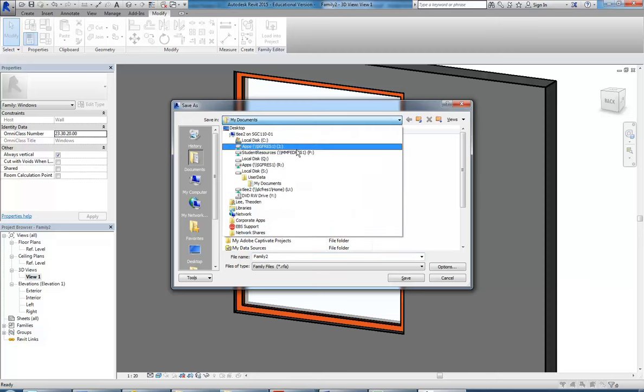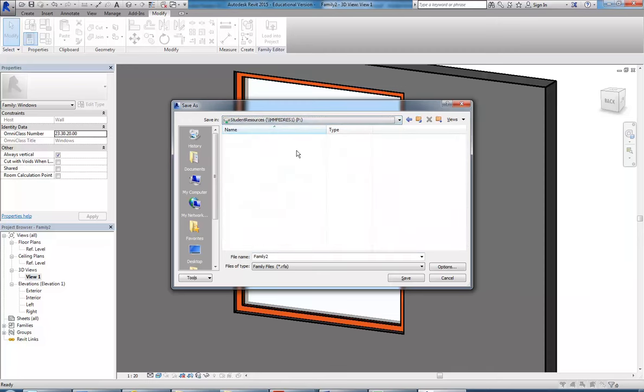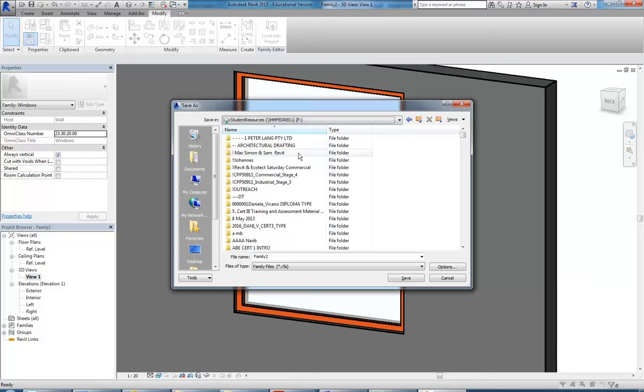So Jenny, the option to change the height and width, that's automatically a parameter that you don't have to add. No. That's right, yeah. But I'm going to show you how to add your own dimensional parameters in a second as well. They're not that hard, but yeah, most families will give you things like height and width set up already. Some of those they don't, there are a couple. Yeah, some don't. So generic families, for example, they don't. So we can just add them. They're fairly easy to add. So, I'll show you how to add them in a second.